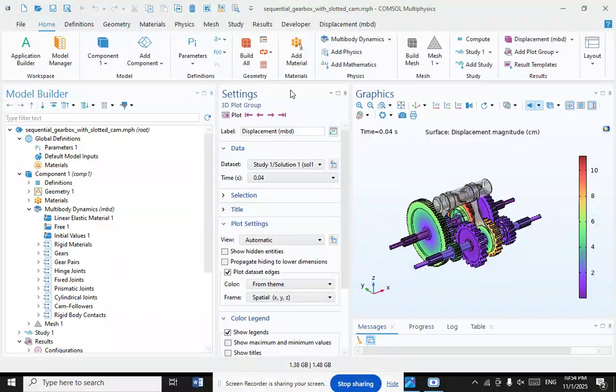However, the output shaft gears are able to rotate independently of the output shaft itself through the use of bearings located between the gears and the shaft. Through the use of collars operated using the shift rods, the speed of the output shaft becomes temporarily locked to the speed of the selected gear.